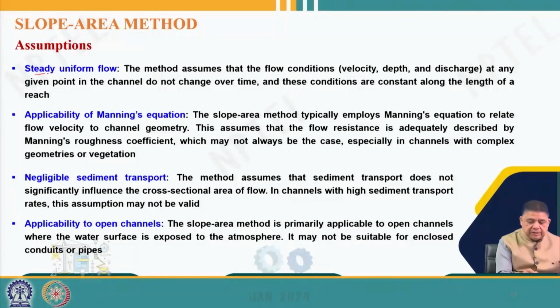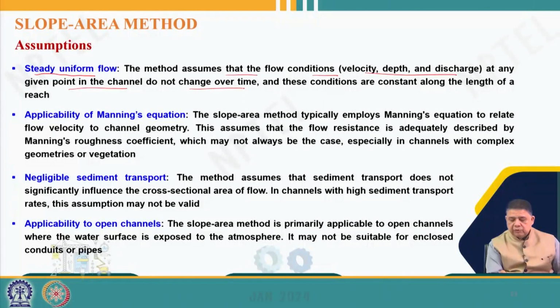So, the flow is steady and uniform. That is, the method assumes that the flow conditions, that is velocity, depth and discharge at any given point in the channel, do not change over time, and these conditions are constant along the length of the reach. So, that is an important assumption.